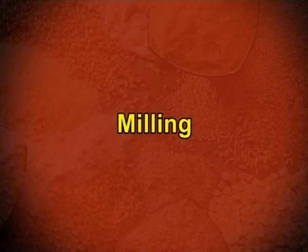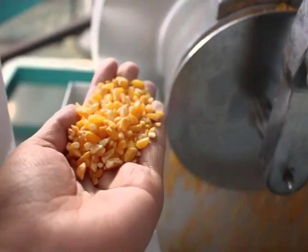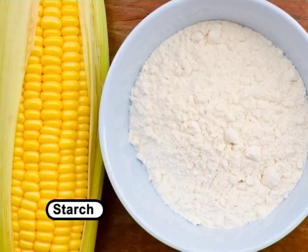Milling. Maize is milled by a dry or wet process. In both processes, the germ is separated from the grain in order to extract and recover germ oil. After degermination, the dry milling employs roller mills and the process is somewhat similar to wheat milling. Wet milling involves a steeping stage and complete disintegration of the endosperm in order to recover starch and protein.